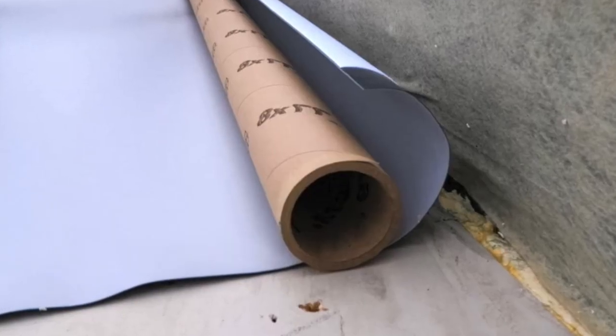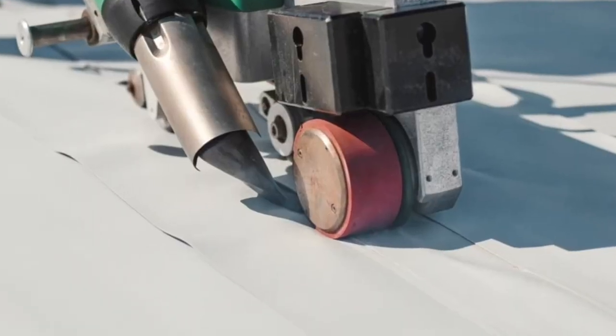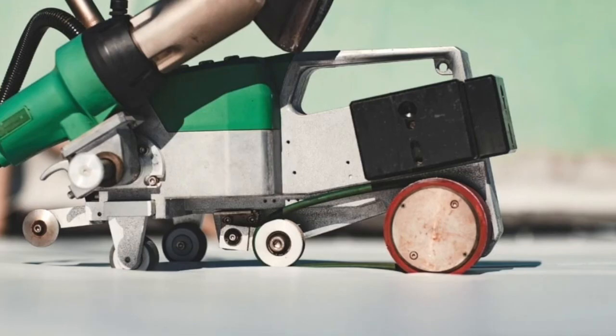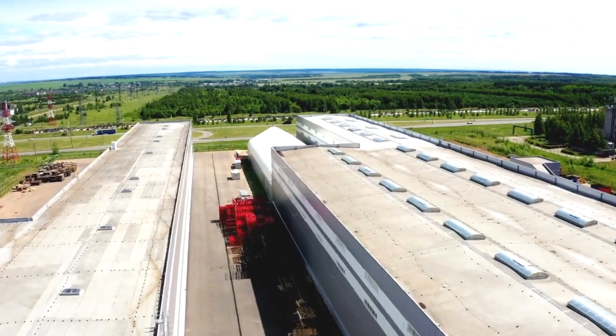Installation. TPO comes in 45 to 60 thousandths of an inch in thickness. It is a little more complicated to install because it does require more equipment and good application technique. TPO is hot air welded together with a machine that runs down the seams and heats the membrane to a pliable surface that adheres to itself. This installation technique seems to be more efficient than EPDM, simply because it is much less prone to separation. This is simply because it is heat pressed as opposed to seamed or hot glued.